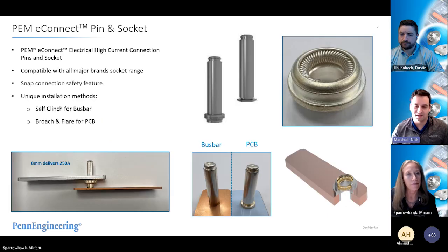So now talking about some other ways that we've been looking at these terminals. The one we've discussed previously in the contact bushing is meant for bolted connections in bus bar to bus bar connections. What we've also been developing is a clinching pin and a clinching socket, which can be installed for quick connections between different bus bars.